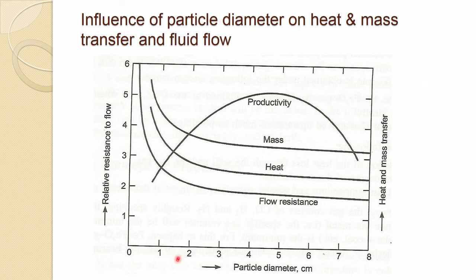And if you look at the plus 20 mm particle size, there is not much difference in the heat and mass. Of course, a little decrease, but it is not substantial. So, one can avoid minus 10 millimeter and can go towards a little larger size particle, and if you look at that way,